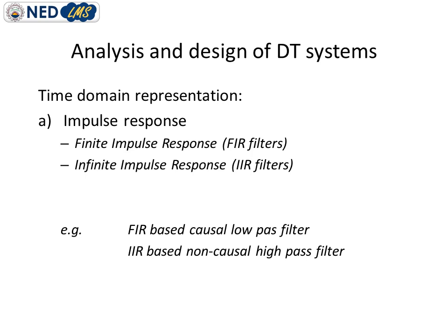So in this way we can represent our system on the basis of FIR or IIR, and also on the basis of causal or non-causal. And what are causal and non-causal systems we have already studied in the initial lectures. And the third is the operation, which is low pass filter. So we can classify any system as this is FIR based causal low pass filter, or we can say this is IIR based non-causal high pass filter or band pass filter.